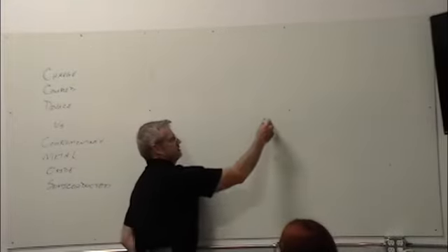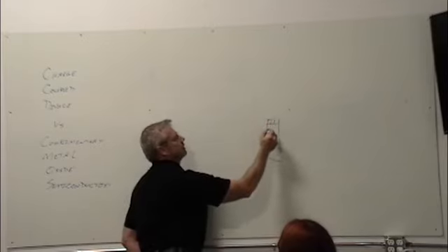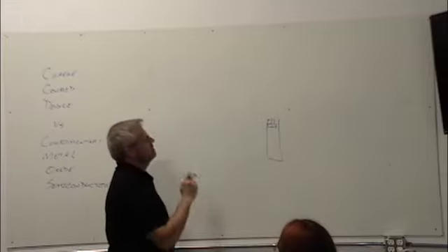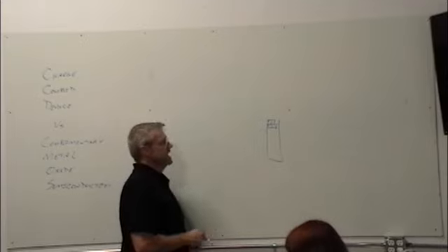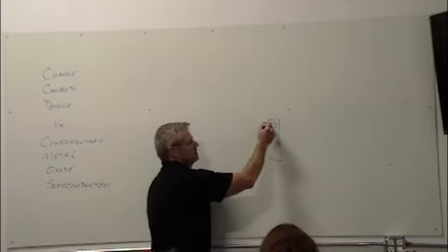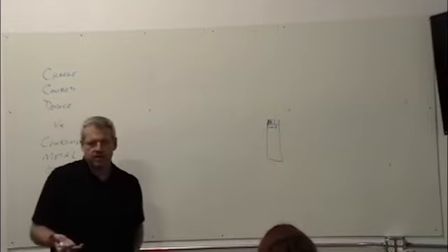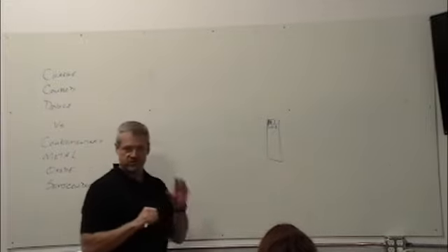There's a sweet spot there, right? If I want to look at a brick wall over here, and I want to be able to see individual bricks, Nyquist says I need to get 2 pixels on a brick, right? So I need 2 pixels in this direction and 2 pixels in that direction. So I need 4 pixels per brick. And probably I want 6 or 8 so I can see that line in between the 2 bricks and discern this brick from that brick.